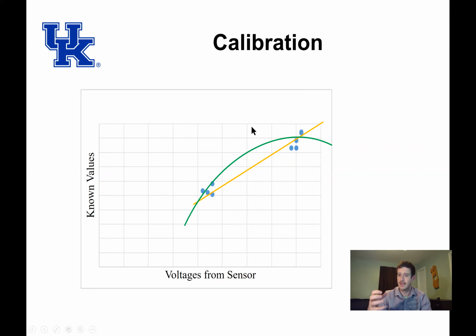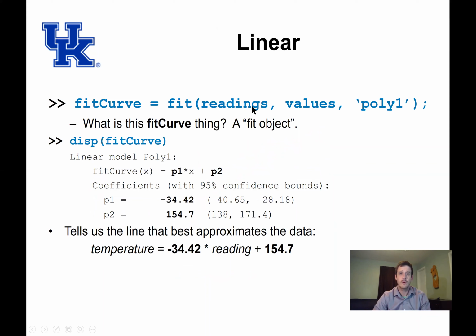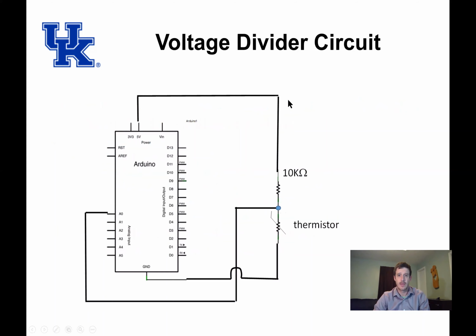And so we're going to use MATLAB to actually predict what those values are for us. The way we're going to do that is we're going to bring in the curve fitting toolbox, and it might already be installed in your MATLAB, but if not, it's just an add-in. So it's curve fit. What it's going to do is take one array of values and a second array of values, just like we had up in this chart.